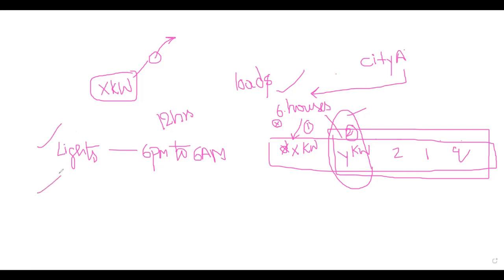And we also know some loads that occur daily during the office hours, maybe in the substation, when the staff will be there. So from morning 10 a.m. to evening 6 p.m., I require some loads for laptops, connectivity, fans, lights, everything. These are some loads daily. We can call these non-continuous loads. These will be there only for a period of time.